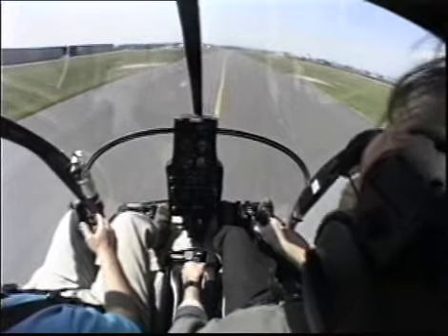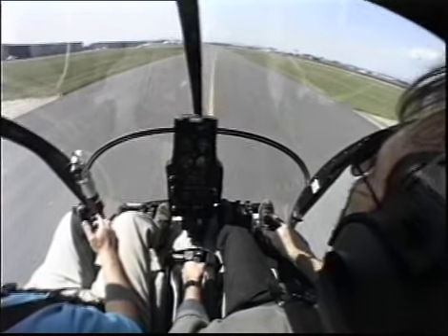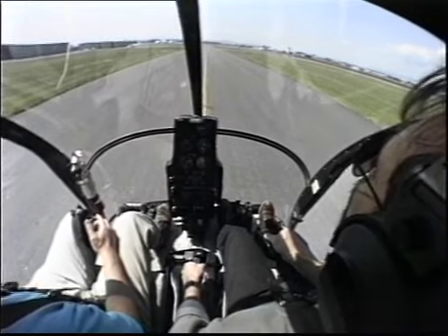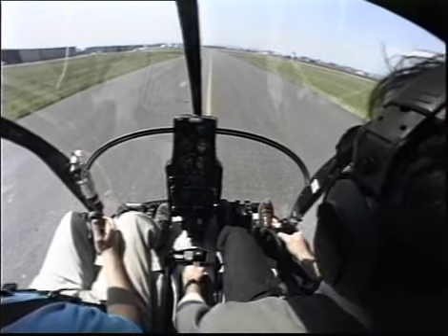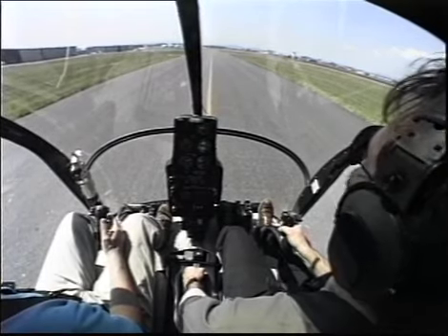Maintain normal RPM during the running landing to ensure adequate directional control until the helicopter comes to a stop. Maintain maximum allowable power. Don't lower the collective until the aircraft has come to a full stop on the ground. However, if some braking action is desired, you can lower the collective cautiously.